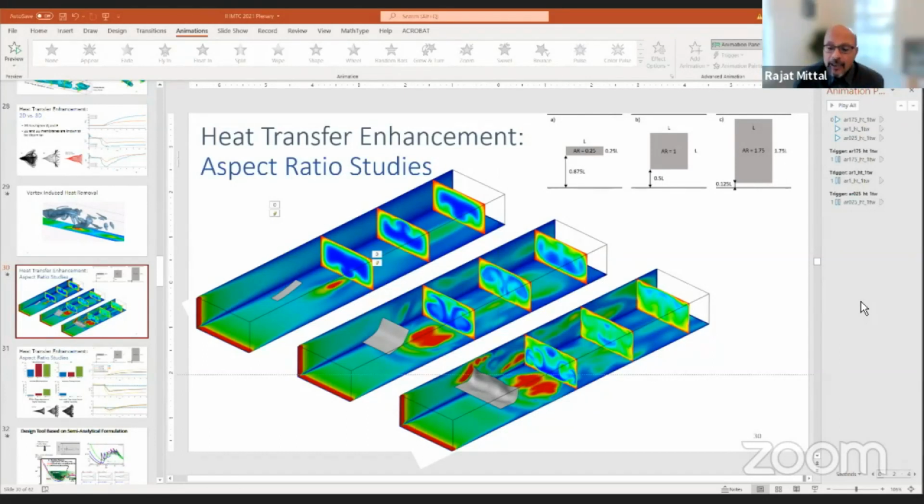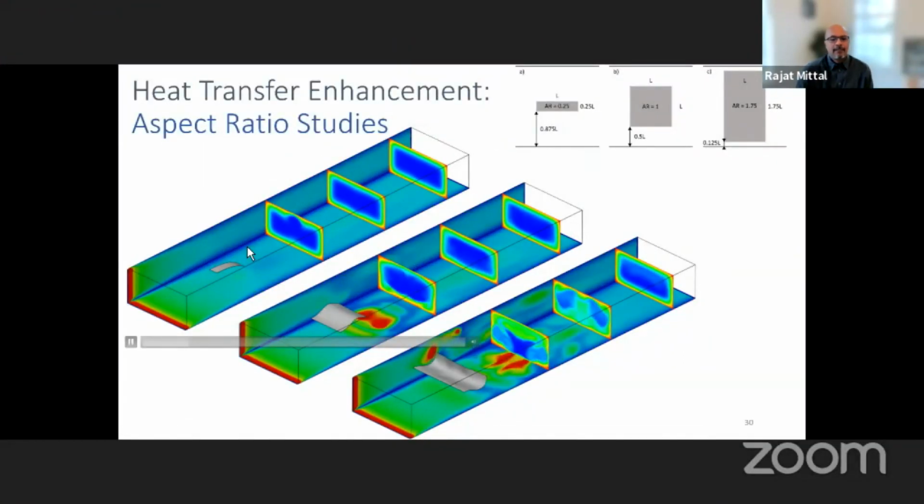Right. So these simulations that you're seeing on the screen right now, these full 3D simulations, are actually DNS simulations. They have been done in the DNS mode, but we can also run large eddy simulations with this code. And if you go to very high Reynolds numbers, then of course RANS models might be the way to go. Some kind of unsteady RANS. Steady RANS will not give you a whole lot because you need to model the vibration of the flutter of the membrane itself. But some kind of unsteady RANS, some kind of detached eddy simulation type of modeling.